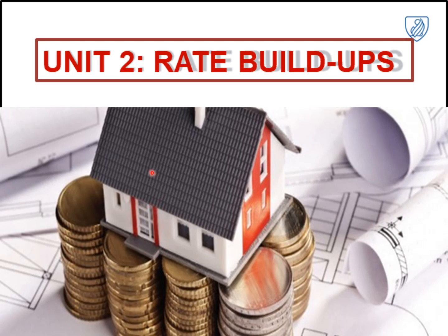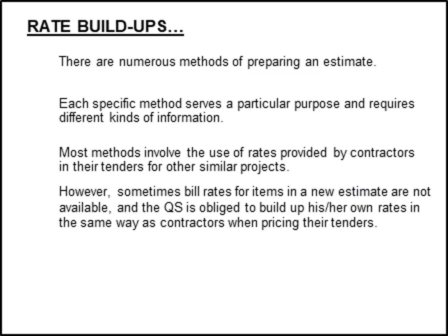Rate buildups. For your elemental estimate, this goes hand in hand with it, and is a way to approach it. The example that was provided will give you the structure, but you always have to refer back to your elemental guide on what is included and what's not included in your elemental estimate and subsequently your rate buildup. The main thing about rate buildups is you're taking existing rates and amending them to be in the correct unit for your estimate.